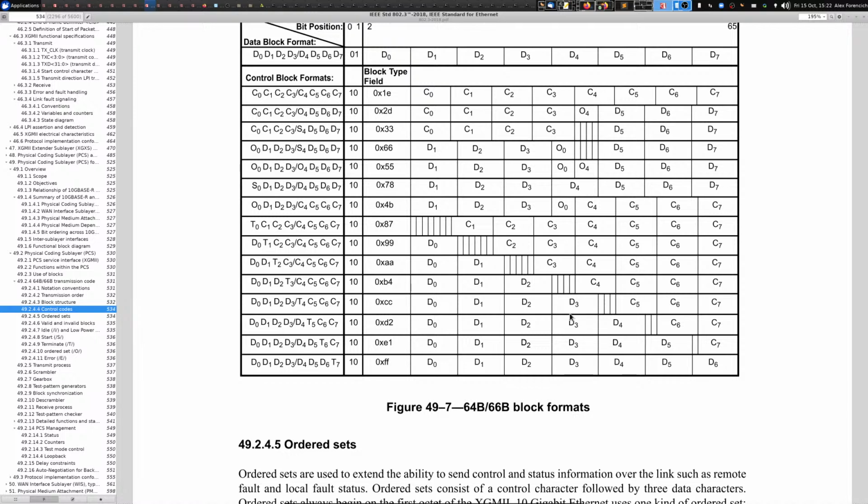So USB and PCI Express tend to report the raw link rate, which is after the line code. So for 8B/10B, that's a pretty high overhead. PCI Gen 1, for example, is 2.5 gigabits per second, but that's after the 8B/10B encoding. If you look at how much data you can actually send in terms of 8-bit bytes, it ends up being 2 gigabits per second instead of 2.5 per lane.